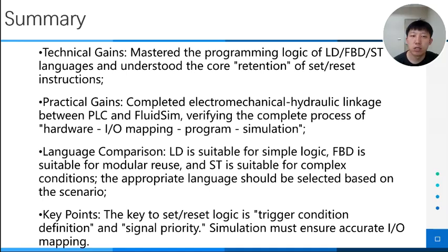Third, through comparison, I found that ladder diagram is good for simple logic, function block diagram for modular design, and structured text for complex conditions.